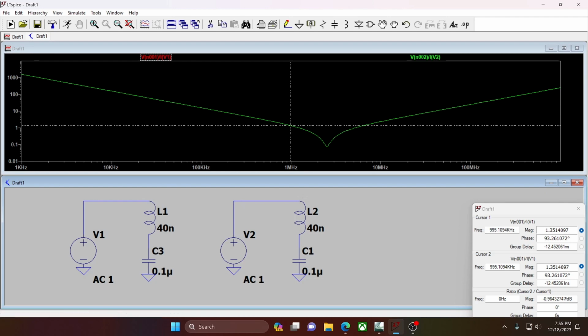So then we have our inductance. This includes everything between the voltage source and the pad of the IC. So that's trace inductance. That is any vias you have. And that includes the ESL of the capacitor. Values you'll find for this are somewhere around 10 to 40 nanohenries. So I just stuck with 40. As you'll see, I'm being a little conservative.